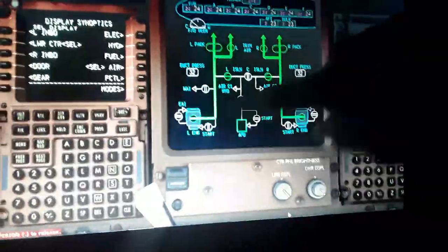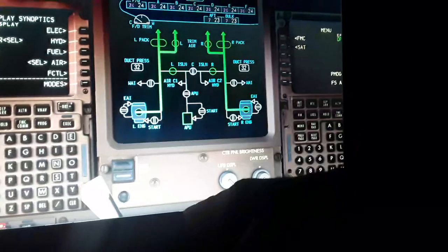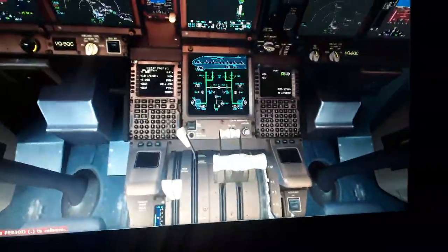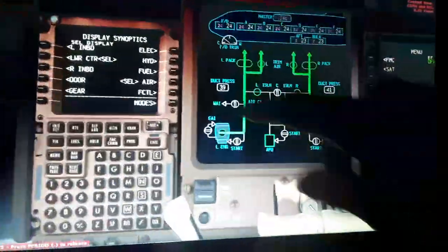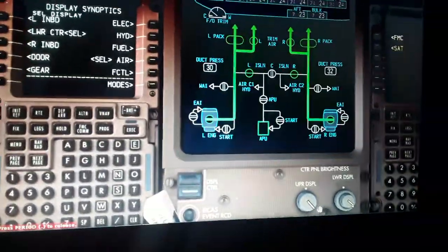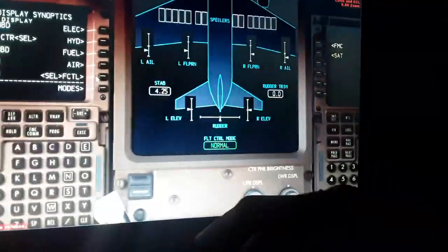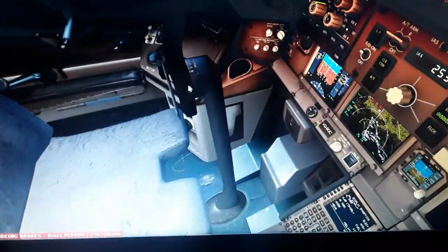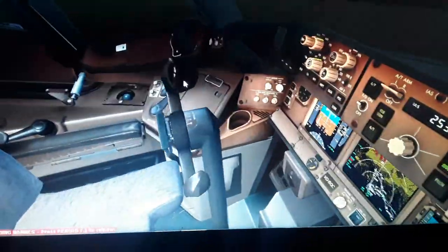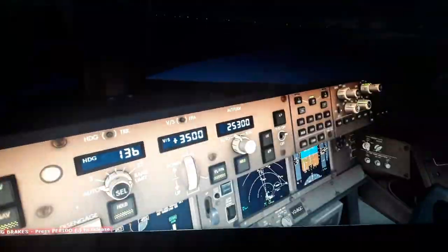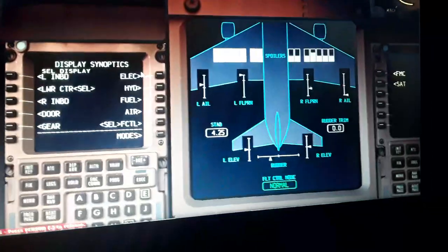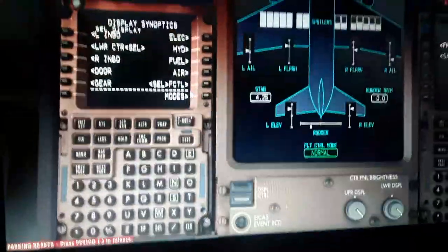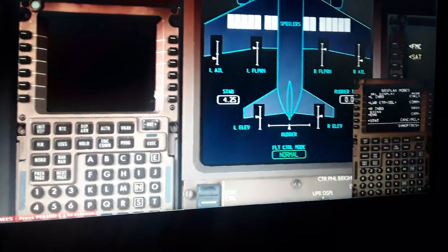The air, the left and right wing, the APU, we need the bleed air from the APU to start the engines. Also some hydraulic fluids, wing and engine anti-ice, air conditioning, ventilation. We need also the last system, the flight controls. Here you're going to see they're all working nicely and freely like this. So we have the flight controls movement here on this side also. It's displayed here, all the flight controls are working normally. Okay, also the aircraft, the stabilizer trim. So we go back